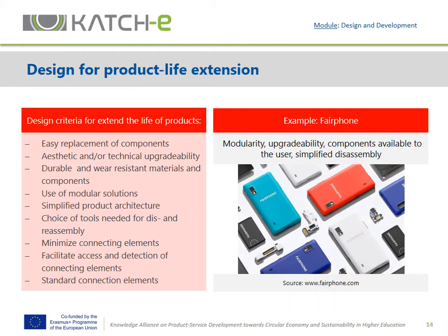In this strategy, the criteria are easy replacement of components, the possibility of an aesthetic or technical upgrade, the use of durable and wear-resistant materials and components, the use of modular solutions, a simplified product architecture, the choice of tools needed to disassemble or reassemble, minimizing connecting elements, facilitating access and detection of connecting elements, and finally using standard connection elements.